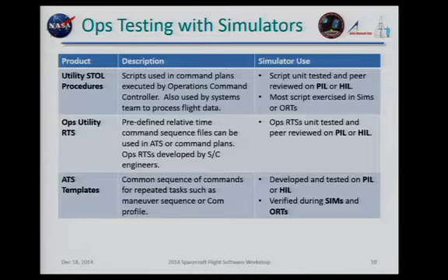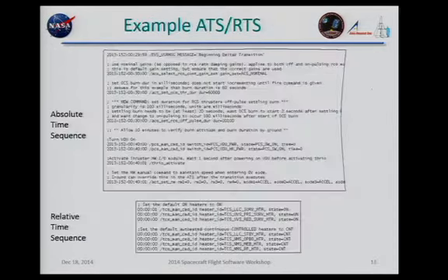And then procedures, these would be more, it's not so much commands being sent to the spacecraft, but it's testing how the operators are going to react. So, for example, when we have lunar orbit insertion, there's a lot of contingency cases that we would have to have basically in our back pocket. So if the software reboots, okay, everybody switch to procedure this, and we're going to start executing these commands. So to get the flow of the procedures, we would run these actually through the HIL with people sitting there and testing them out. So that's the testing phase, so that's pre-flight.